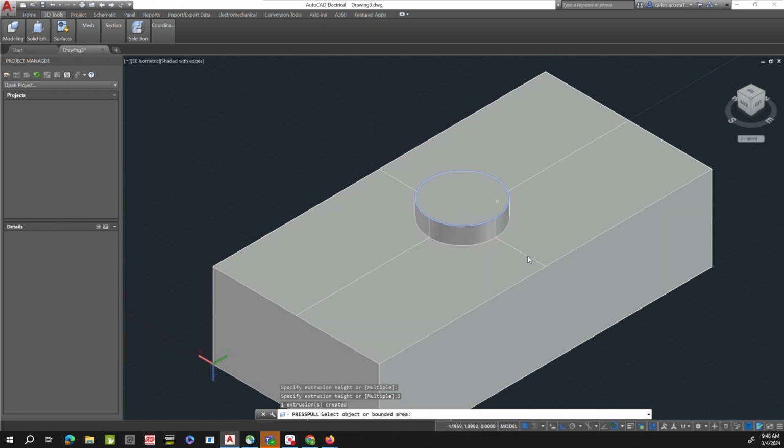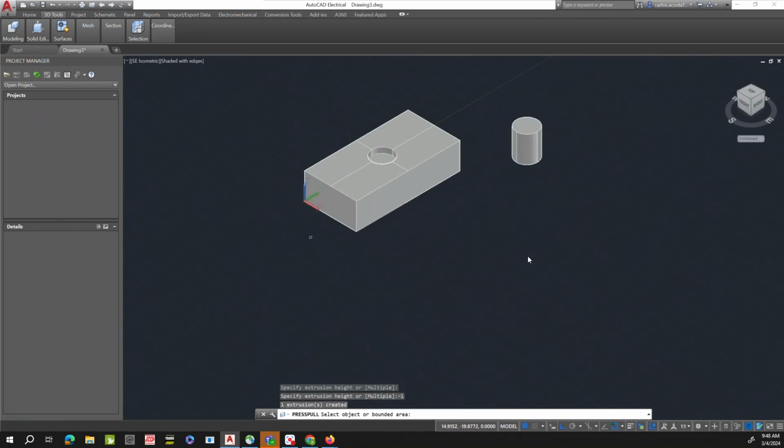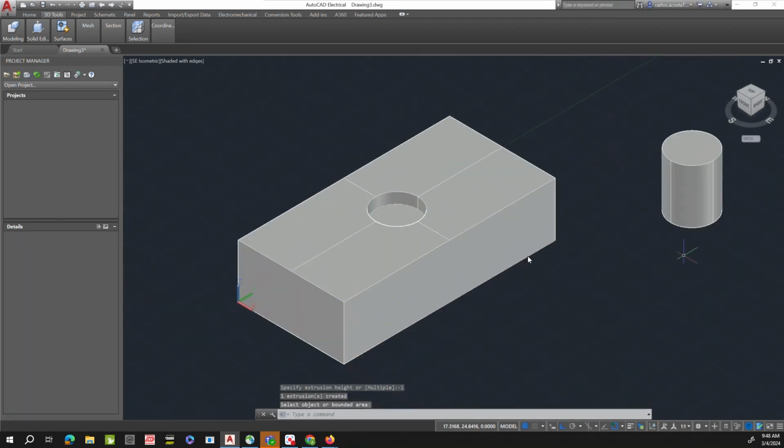going to extrude material. I don't want that. I want to cut through the material. So I do press pull, I select this circle, and I do -1, and then it cuts through the material. This is because we created a relative point of reference. Now we're going to do -1, meaning it's going to go down from the point that we're selecting. All right, so this is how you use the press pull and the copy edges to do different extrusions or cuts.